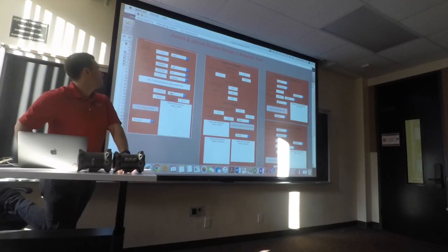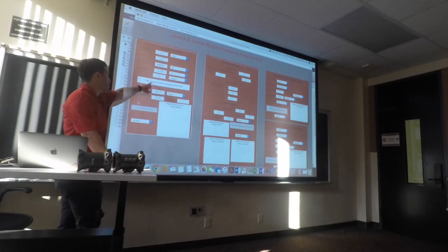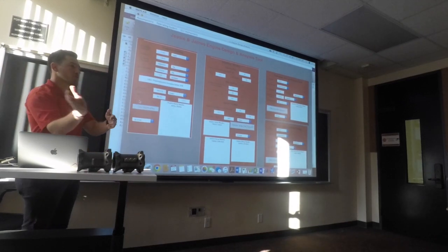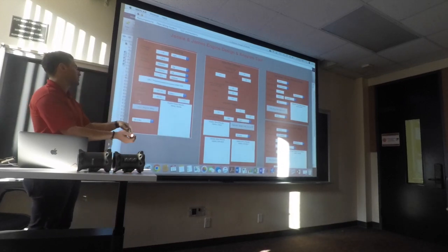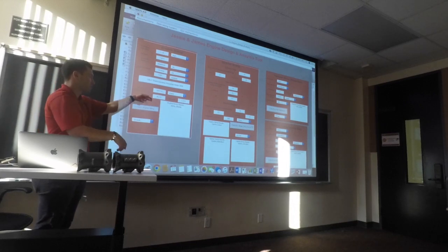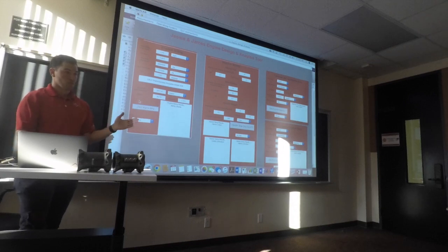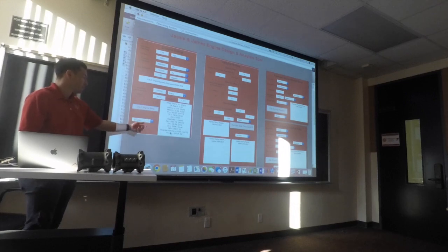Let's see. I haven't run this. So the way this GUI works, like I just mentioned, you have the design point here. You press calculate. This now goes on the NASA CEA website, inputs all this for you, runs the simulation, takes the text file, imports it, pulls it from the text file, and displays it. And now those equations that we just went through, remember, those take forever to do by hand. You literally just press this, and then bang, it's there. Now we know the OF ratio, M dot, A star, D star, ME, DE, ISP, chamber volume. Right?